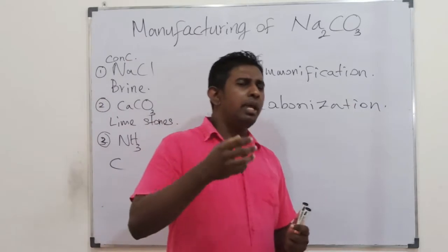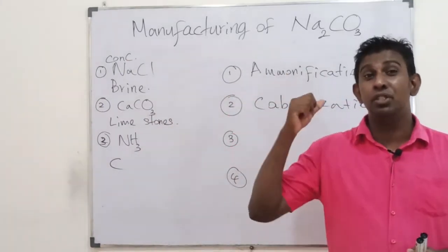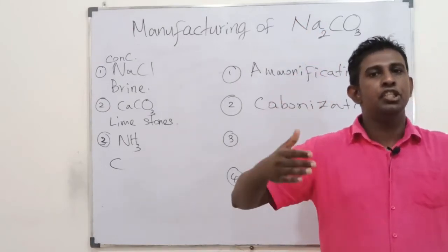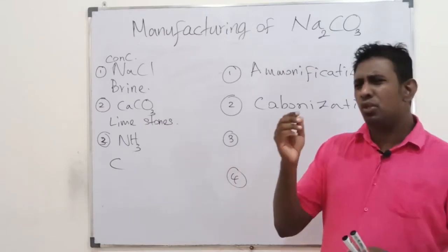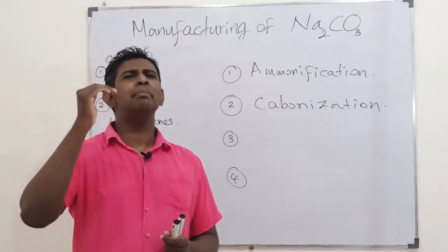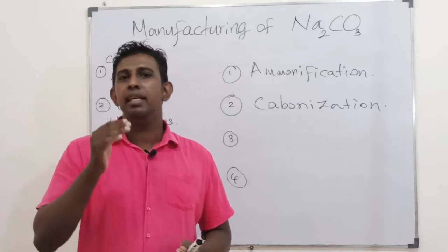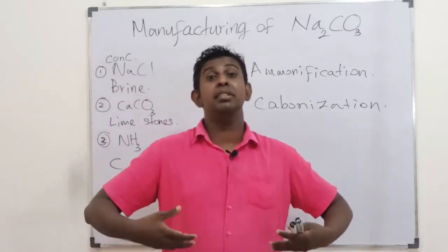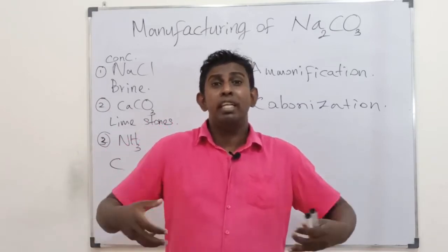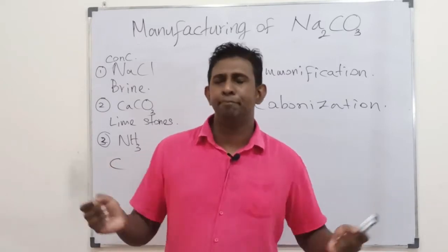Then when you have these exothermic processes in the first 2 steps, the temperature would increase with the heat it releases. So it's quite a disadvantageous thing. Because at high temperatures, the dissolution of gases would be less, for the reason that gas dissolution is exothermic. Therefore, at lower temperatures, you could dissolve more and more gases in water.